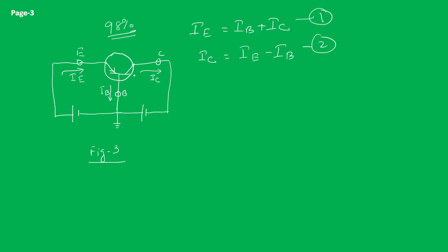So this is the relation of the currents, and the direction of currents is very important here. The flow of current here is mainly because of the holes, so the direction of flow of holes and the direction of flow of current will be the same. Now if we vary this voltage here, then the magnitude of IB, IC and IE will also change. But a large part of the emitter current, IE, flowing into the transistor constitutes the current in the